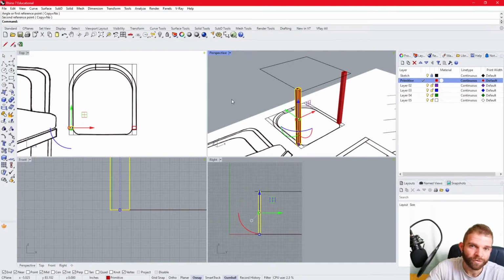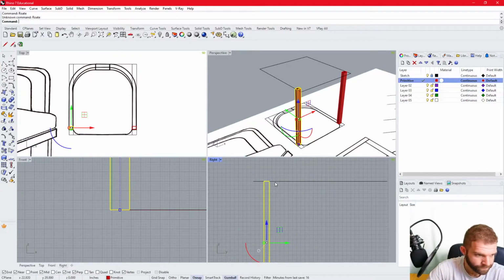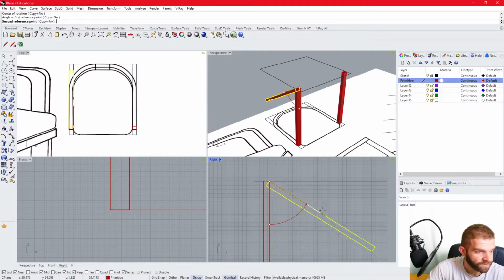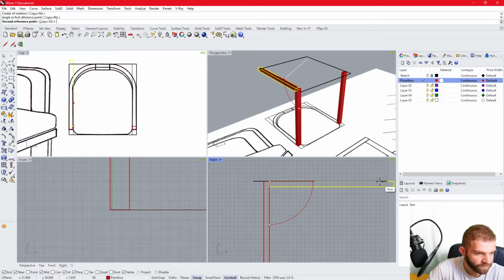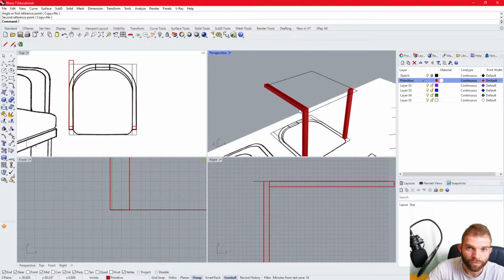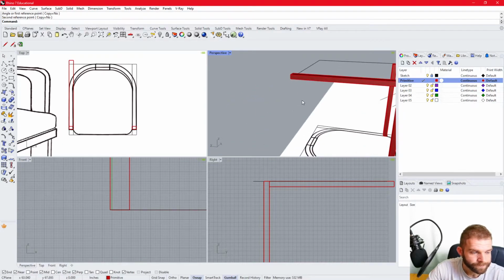What I want to do is I want to create the horizontal side of the armchair. So I'll go ahead and go into my side view, and I'll use that rotate tool to use the correct axis. And so that will allow me to snap onto the line that I set up for myself that's horizontal, and there I have my arm.